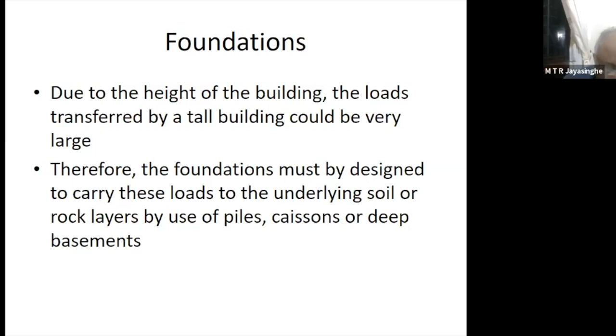And he knew very well that it's not going to move. When the geotechnical engineer proposed a capacity of 6,500 kilonewtons for a 1.2 meter diameter pile, the structural engineer said 11,700 kilonewtons. It's close to double.